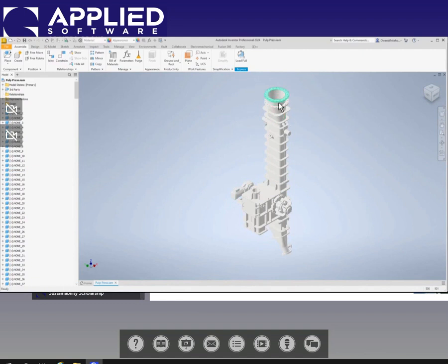It hasn't actually fully loaded this thing. It's actually just sort of partially loaded it. And you can tell that by looking right over here where it says load full in this express button. And what that means is this model is just kind of being shown in a fast loading representative view.